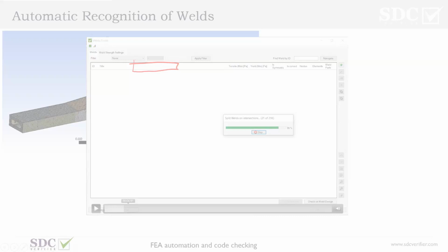But in general, you can do it in two steps. First, you do everything according to the drawings, because we engineers, in the end, believe these drawings, unless anything else is mentioned. Then if we see that the situation is more than acceptable, most likely you will not have serious problems at this local spot, which your manufacturer forgot to mention, the very small plate.